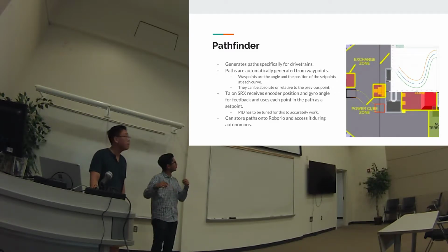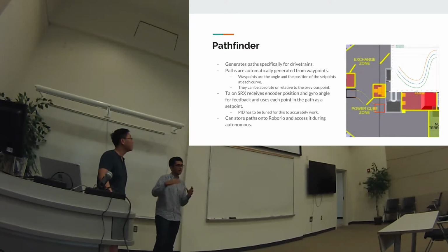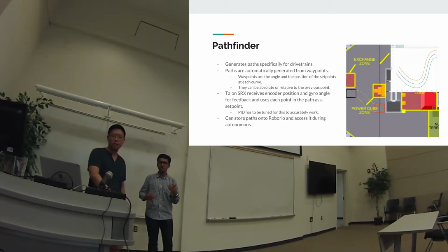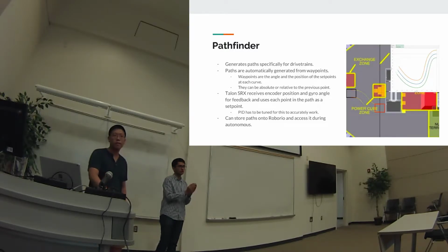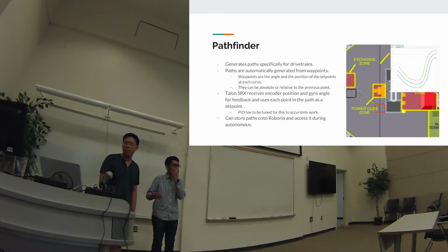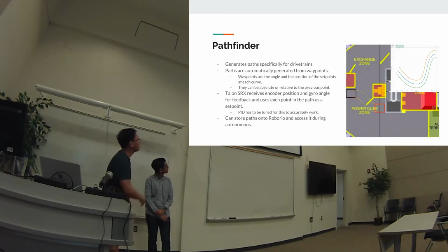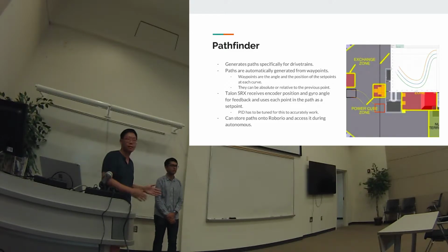So what Pathfinder actually does is when you're writing the code, it has a tank drive and a swerve drive implementation. With the tank drive implementation, you really just put the sensors that you're using and the motors that you're using, and it outputs the value that you have to send to Talon SRX. So it doesn't work built into Talon SRX, like Justin was saying, but you use it separately, and then you provide those values to Talon SRX. Yeah, and one more thing, the curvature while we're driving is not an open loop problem. We're purposely driving that spline in order to get to the position.